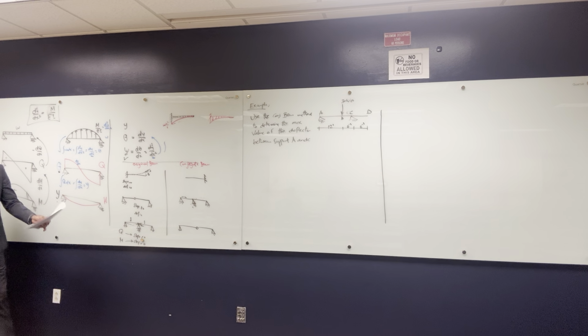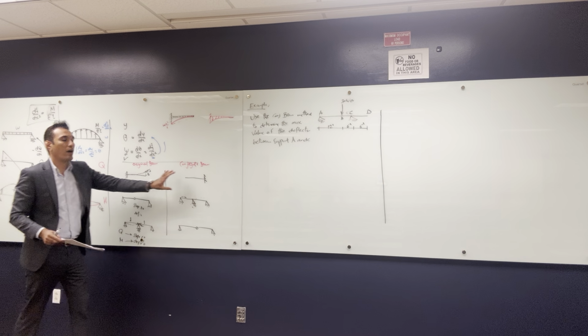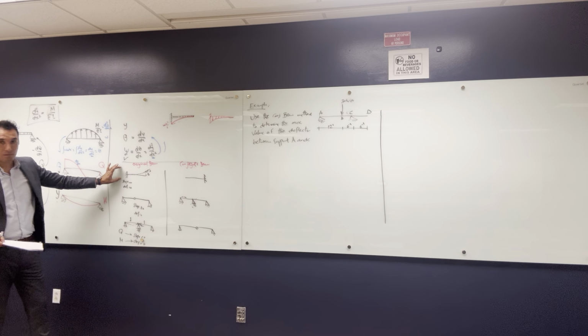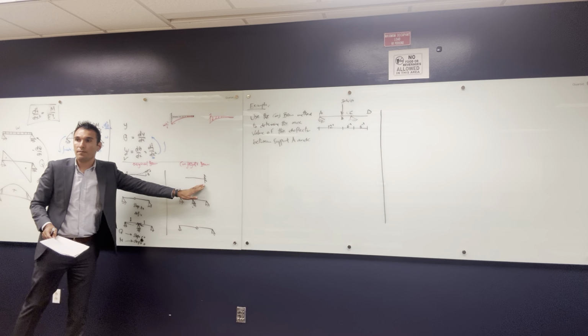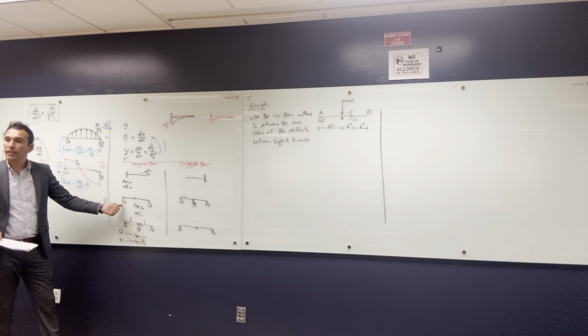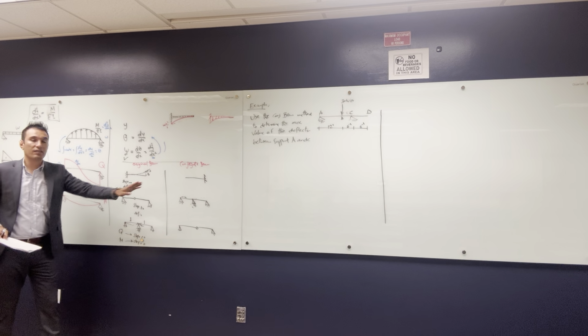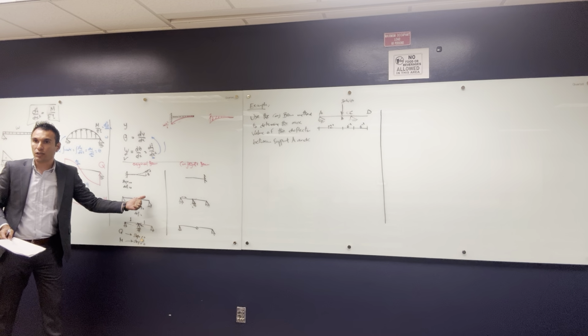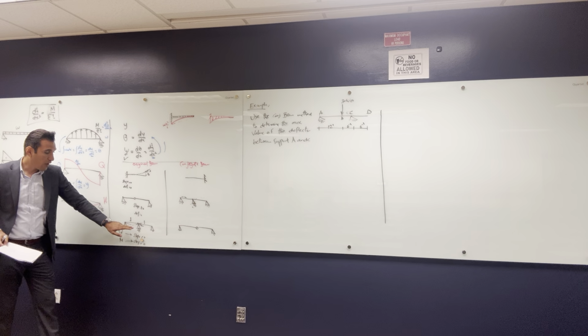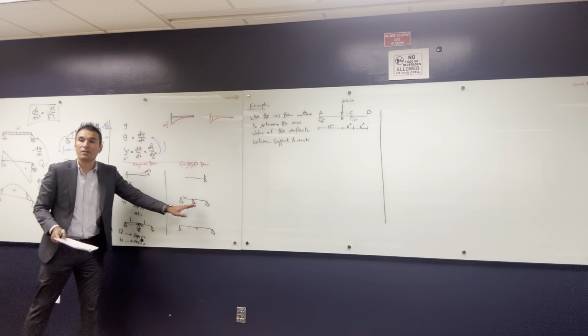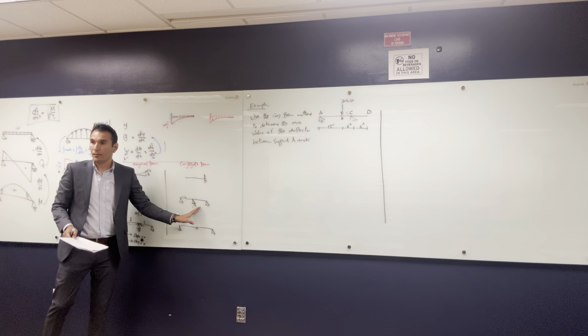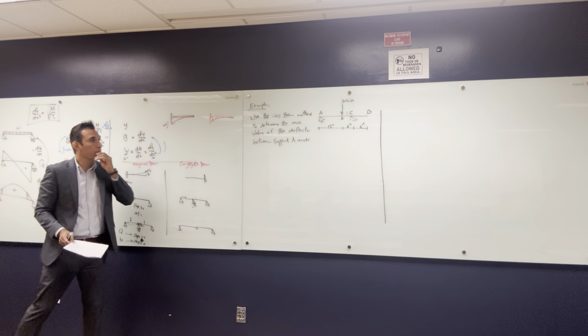So, as a summary, you should transform the boundary conditions. Fixed is gonna be free. Free is gonna be fixed. Okay? Any hinges or rollers at the ends are gonna stay hinges and rollers. We are not gonna change them. And if you have a roller in the middle, it's gonna be an intermediate hinge. And if you have an intermediate hinge, it's gonna be a roller. Okay? Those are the 4 things that you should know.